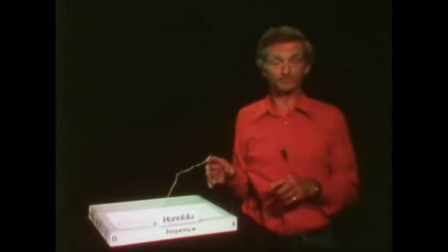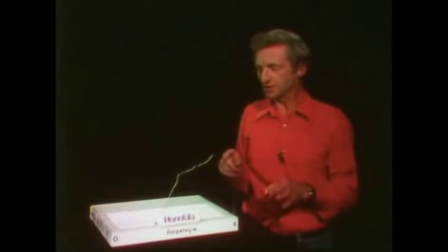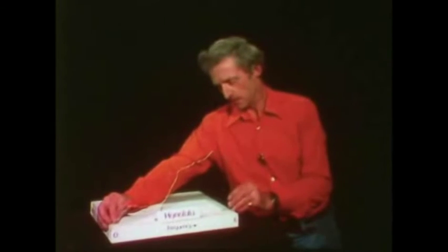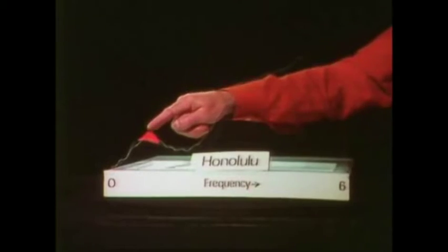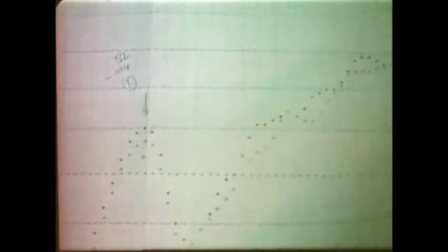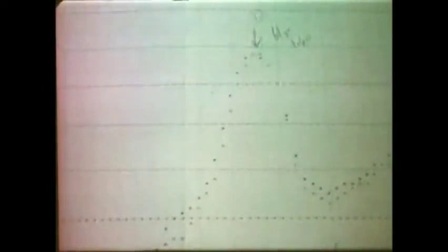So let's think about how that would affect our energy density spectrum. Now, those first arrivals would be expected to add a peak to the energy density spectrum at the low frequency end. Something like this, in fact. And that peak there represents the energy added by the first waves to arrive from the storm. Now, we've actually got the computer results for those early arrivals. Here's the first one. And because of dispersion, at each successive recording, the peak moved to higher frequencies as the shorter and slower moving waves passed through.